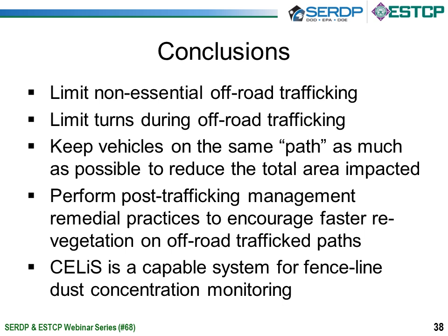Thus, there would not be an appreciably elevated risk to wind erosion unless or until successive passes along that same path are conducted. In this situation, it would normally be desirable to spread out the vehicles horizontally and not have them all follow the same off-road path, reducing the full cumulative damage effect of multiple off-road passes. Since such conditions would normally preclude the need for remedial action to reduce the risk of wind erosion, it benefits the DoD and the environment to forego such remedial management actions.